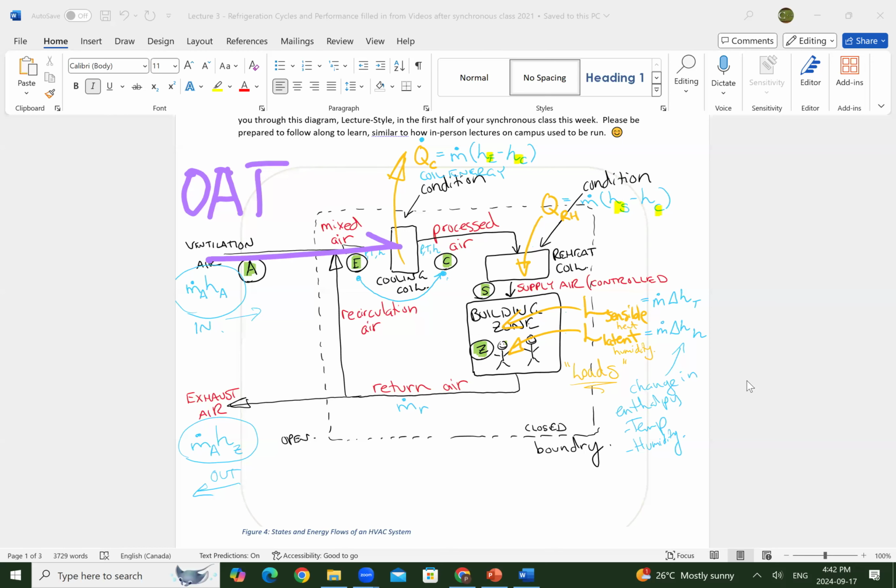And that nice fresh air that you bring in, the problem with it is it's usually too hot or too cold, especially where I'm coming from making this video right now. I am in Southern Ontario. So I have to cool this air and I have to heat this air, right? This air that came from ventilation, I'm not talking about mixed right now, I'm talking about ventilation, has to be cooled and heated.